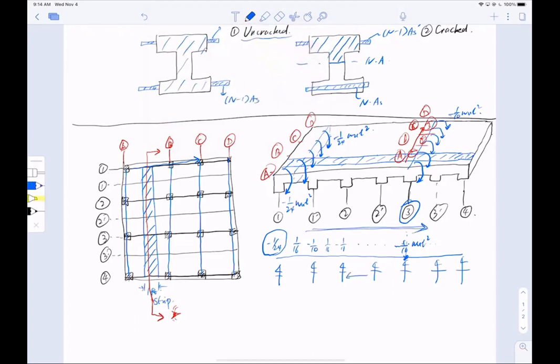That means you need to care about this, you need to care about this. For example, if the question asks you bay 3, you only care about this span length. For example, this is Ln left, I call it Ln right. You can call it 1 or 2, doesn't matter, but Ln right divided by Ln left has to be smaller than or equal to 1.2, the 20%.